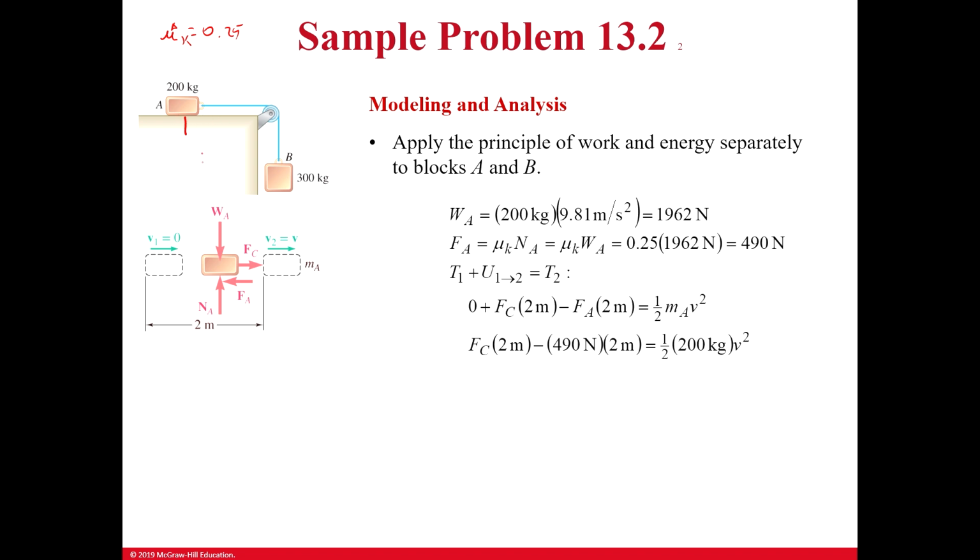The weight of the box acts vertically down, with a mass of 200 kilograms, so that force is 200 kilograms times the acceleration, 9.8 meters per second squared.